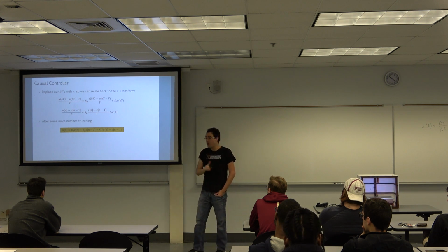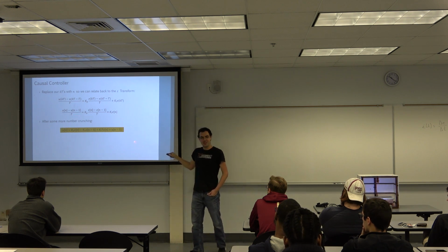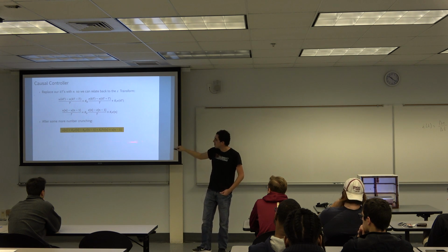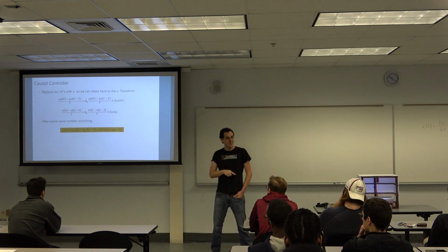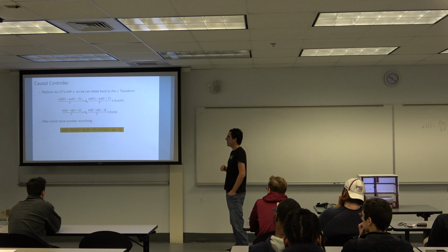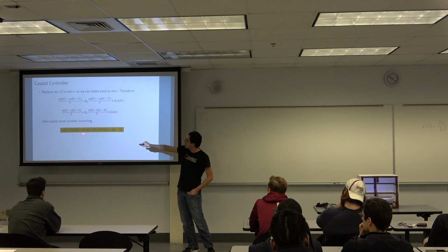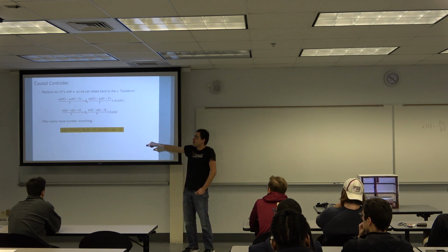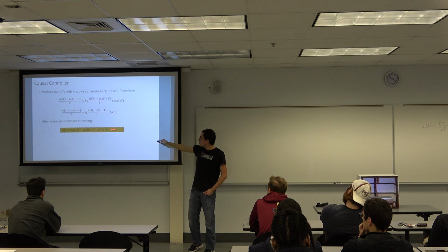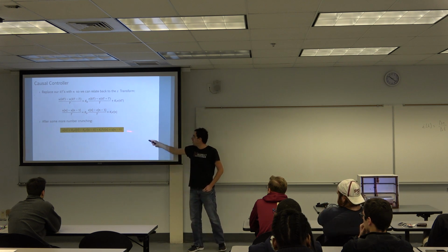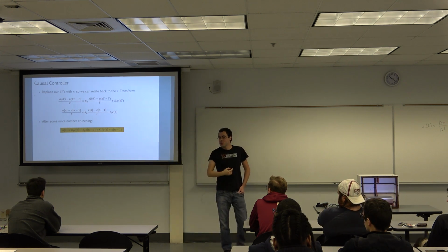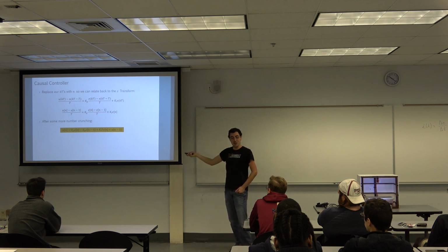Can you realize what we accomplished with this? There's something very important about this expression. u(n) can be calculated now from discrete samples. From the past samples. Past samples, yeah. Right? From the current measurement, e(n), which embeds the current measurement, and the past errors and the past control inputs. So this means that now we can implement this in code.